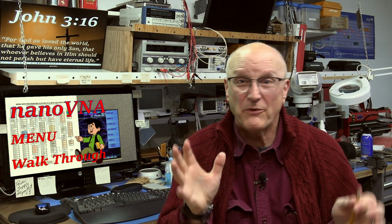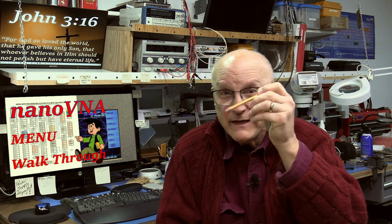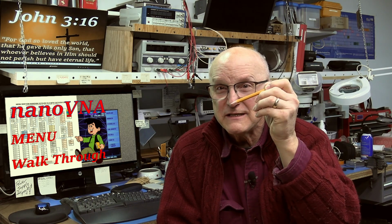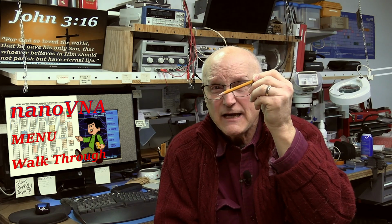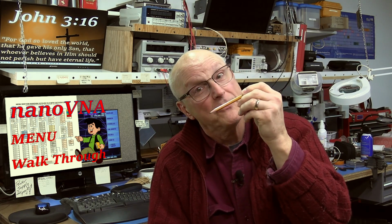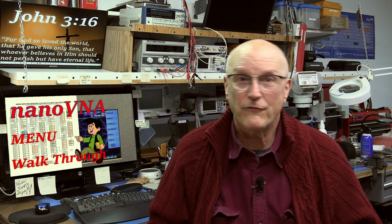So what is a marker? Well, you can think about it as a pointer. You have a nice graph of values on a piece of paper, and you take your pencil and point to the spot on the graph, and the pencil says, "The value at 51 megahertz is 36.1 ohms. Thank you." That is what markers do for you. You can have up to 4 markers defined, and each marker will display its information in a format commensurate with the display format that you chose for the selected trace.